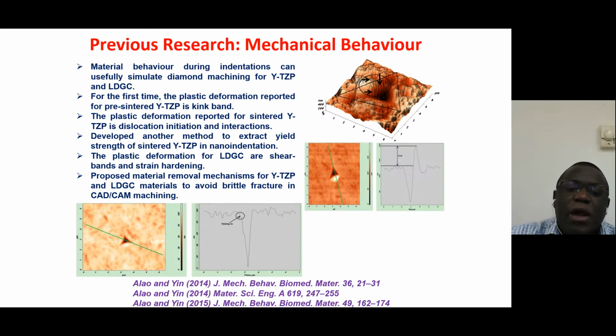Now, the field of mechanical behavior of materials deals with the deformation and the fracture of materials under applied load. This deformation can be elastic deformation, plastic deformation, and in the case of a polymer, can be viscoelastic or viscoplastic. So these mechanical behaviors are influenced by the application of load, and we can study the mechanical behavior of a material using indentation.